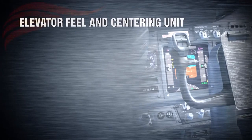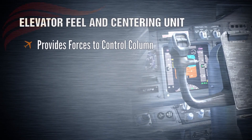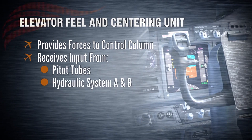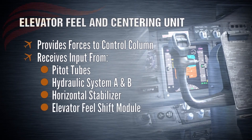The elevator feel and centering unit is a computer that gives variable control column forces as the airspeed changes and the horizontal stabilizer moves. The elevator feel computer receives input from pitot tubes through pitot ports, hydraulic system A and B, horizontal stabilizer, and the elevator feel shift module, or EFSM. This last mechanism operates during a stall, providing 850 psi of hydraulic system A pressure to the elevator feel system.